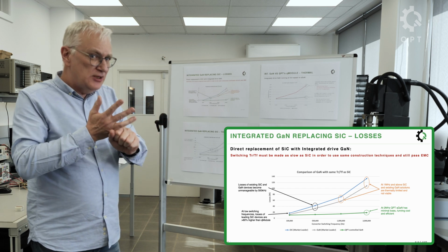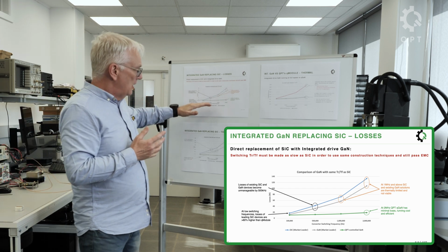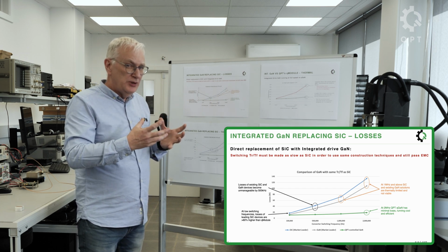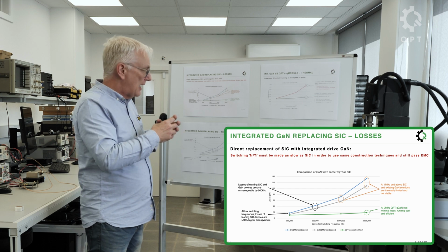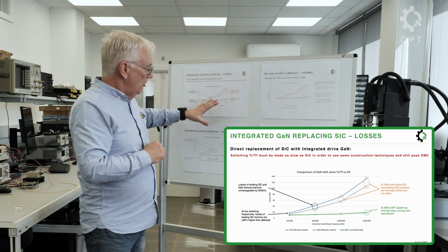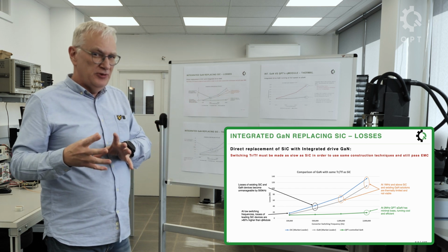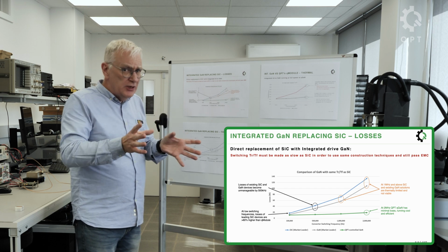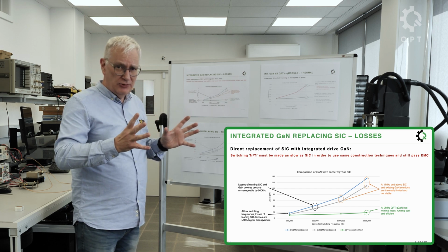Firstly, it's switching in 2 nanoseconds or less. So the amount of power that we're dissipating or losing every time we switch is very, very small. So we're not actually throwing much power away. Secondly, we've got incredibly low thermal resistance. So normal packaged GaNs, as we spoke before, they're very small devices, very difficult to get the heat out of them.